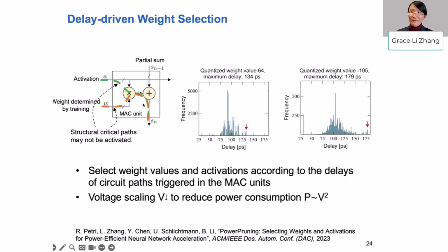That is called dynamic timing analysis, so that we can use it to obtain, for each transition, what the delay is. You can use some tools to extract them. And by the way, I use open source NAND gate libraries when we construct these multipliers and adders.